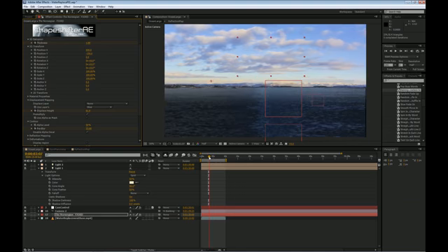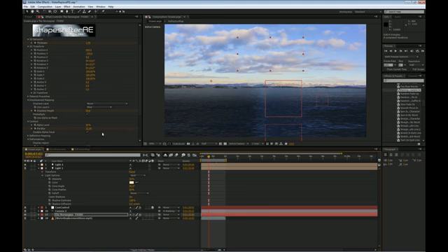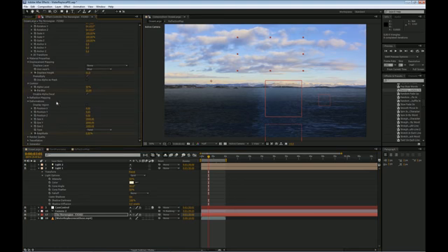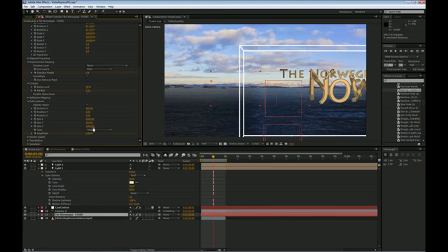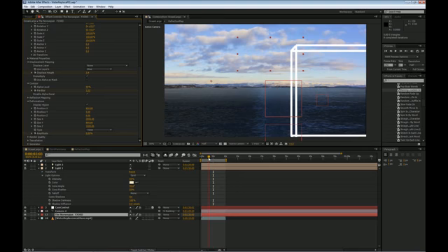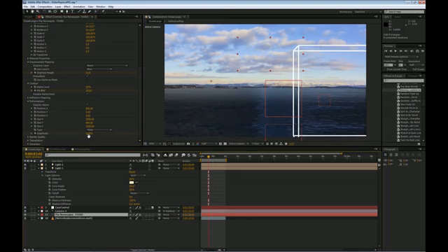Also, what I want to do is animate the twist, as I told you, under deformation in Shapeshifter. But in order to do that, I need to set up my deformation box. So I'm going to display the deformation region, and I'm going to move it on the X to 800, and change the size of it on the Y-axis to 800, and on the Z and X I'm going to leave it exactly the way it is. Now I can go back to 3 seconds in, 3 seconds in 1 frame to be more precise, and bring up the twist to 100%.